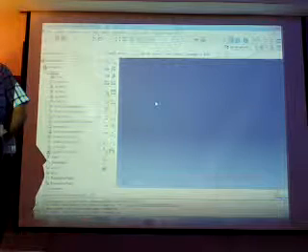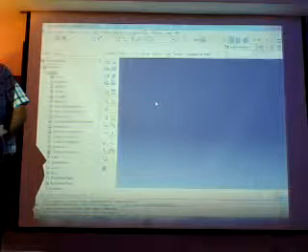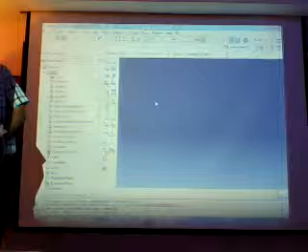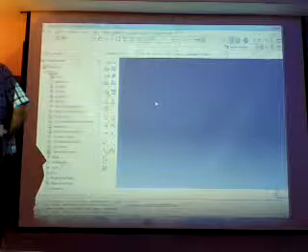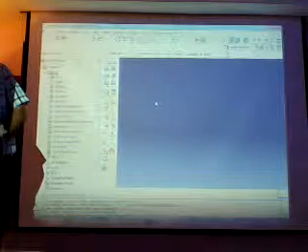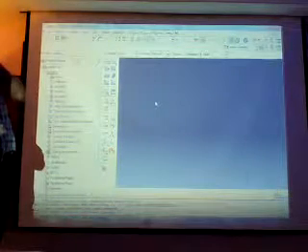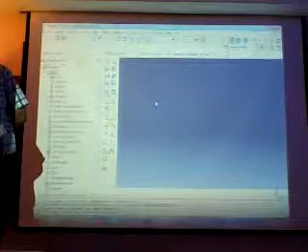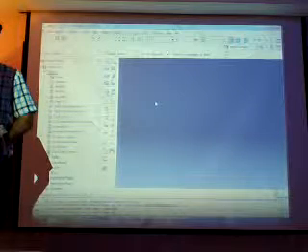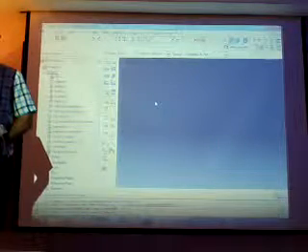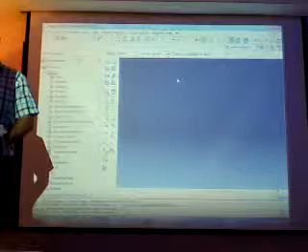Okay? Do we need model reduction? Model reduction. Yes. It is a cylinder, a billet, cylindrical, and we are going to extrude it to 5 centimeter. So we have symmetry. Then we can even reduce the section to become a half model. Half model. Okay. So this is the first part. So now we are going to do the half die and half billet.